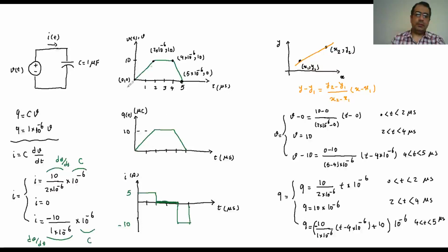But you see that here when we have the voltage changing and increasing, the charge is built up on the capacitor. So the voltage increasing, the charge is going to build up, and throughout the time that charges are built up, we'll see that the current is going to pass through that capacitor. And then as soon as the voltage becomes constant, the charges become constant, and it doesn't let any current go through.